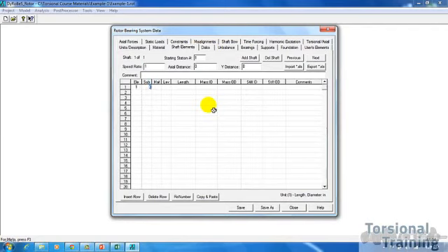And under sub, click on and type in 1 as well. Now what the sub is, for very long rotors, for very big models, it's very useful to use sub elements because it helps with reducing the computation time. In our particular case, since we're building one element, it doesn't matter, so you just keep one sub element. Now under material, type material 1, and I'll explain why you type material 1 in a second. Under level, type 0.